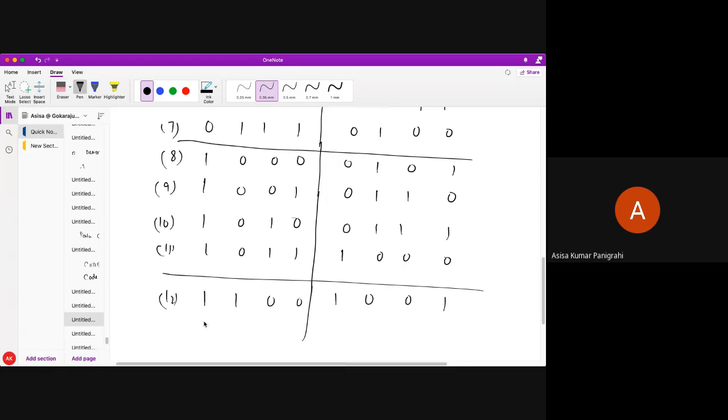Okay. Now, very important, 1101. 13. 13 means 13 minus 3 is what? 10. Is 10 present in my BCD? No. Okay, 10 is not possible because valid BCD is 0 to 9 only. So 10 is what? All don't cares. Do you all understand? So it's very important. Valid BCD is always 0 to 9. This is your valid BCD.